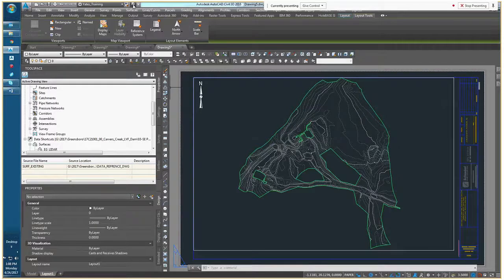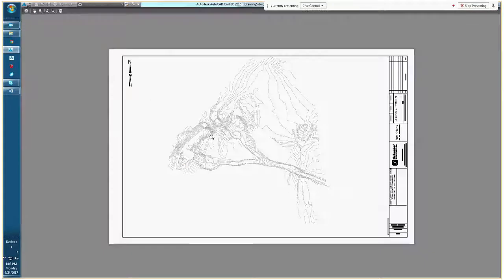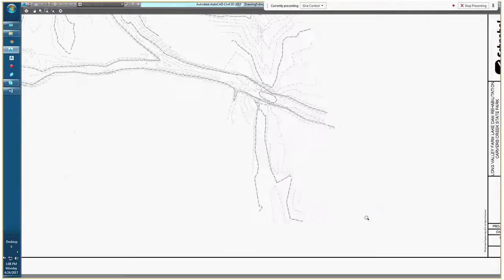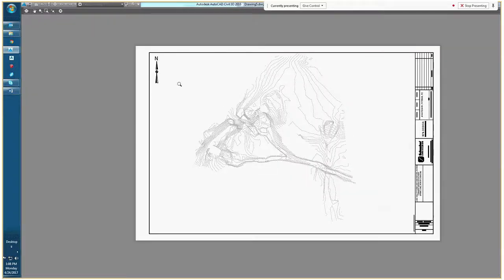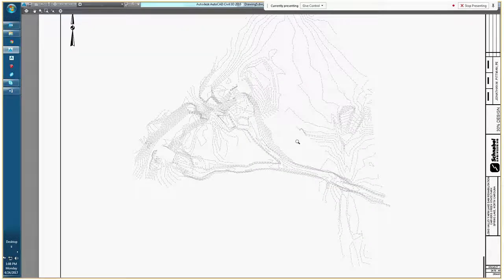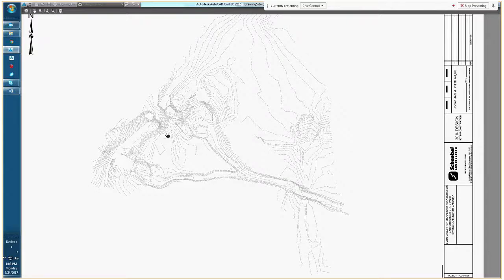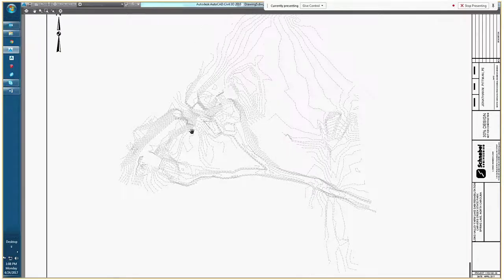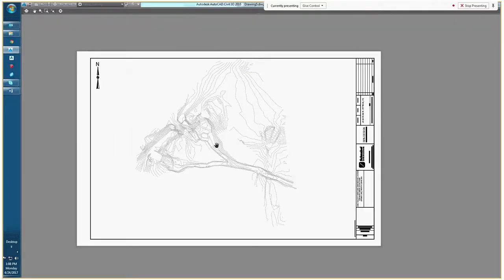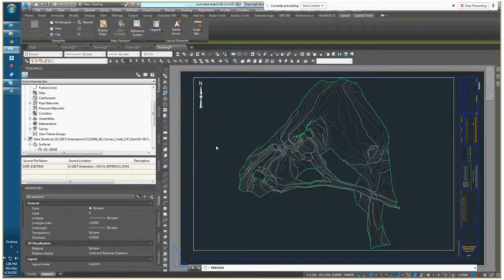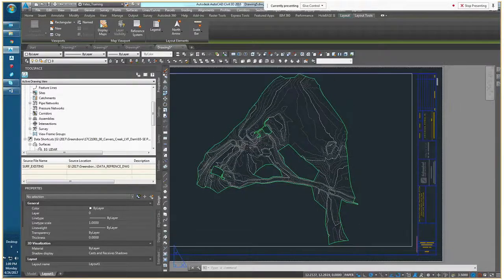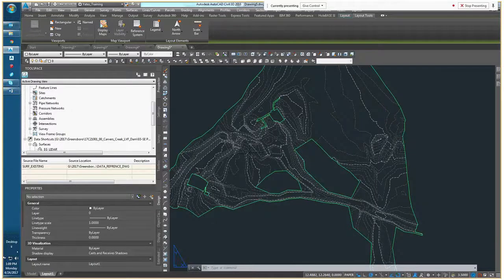So again, if we go to Plot Preview, after turning that viewport to the Defpoints layer, we'll see that the line that represented the outside of that viewport is now gone. But we can still see the objects through the viewport perfectly fine. Okay? So now we have this existing grade surface from a surveyor.